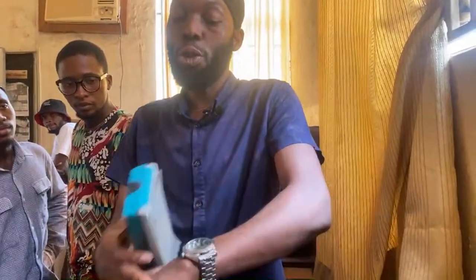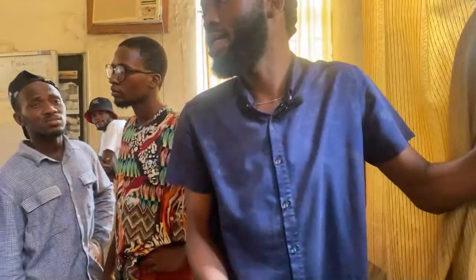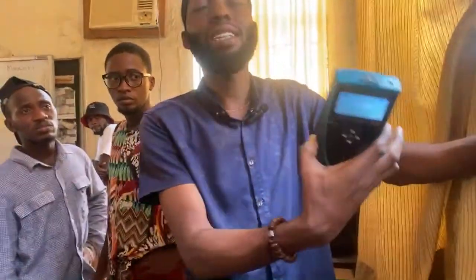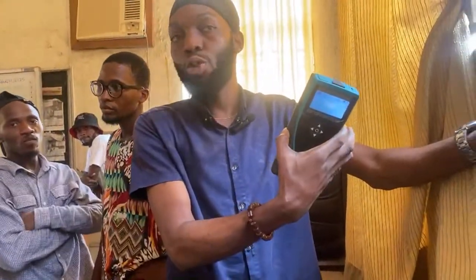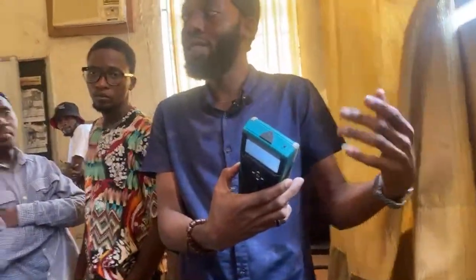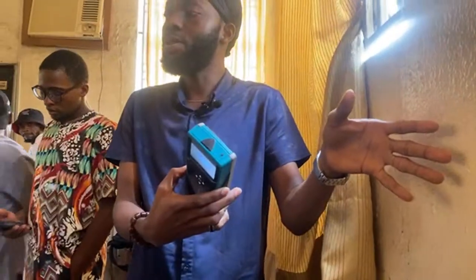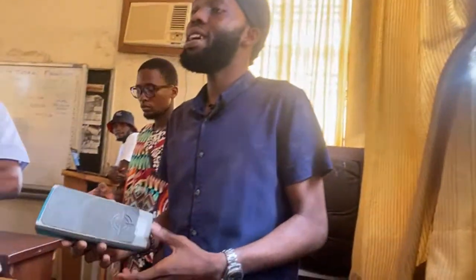If it's a metal, like now I'm using a wristwatch here, right? If it's dropping into my hand here and I'm trying to use the detector, it may affect the reading, because definitely it will notice that there is a metallic object on this side of the rebar detector. You understand? So it will conflict with what I want to check inside the wall. It's seeing something outside which is easier to detect, rather than something inside a structural element. So it will reflect. Rings or watch, anything metallic, it will detect it.